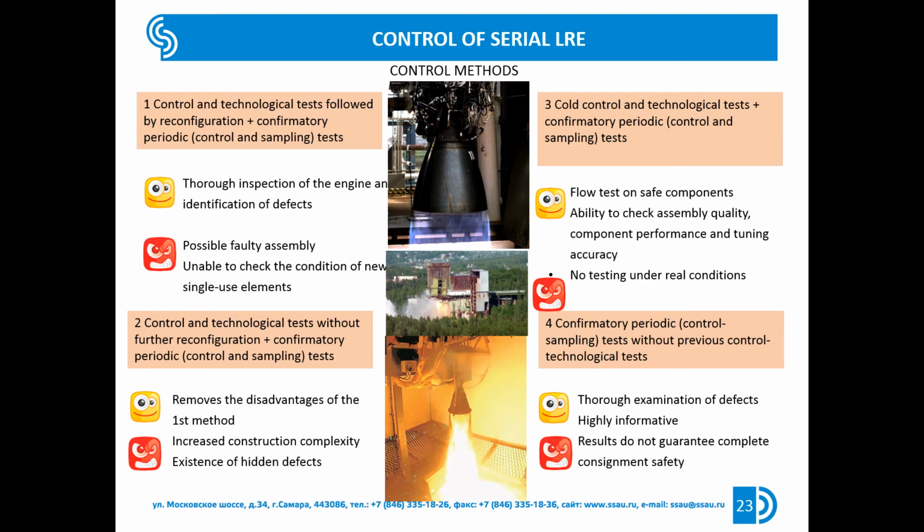This disadvantage is eliminated by the second method. However, in this case, additional requirements are imposed on the design of the LPRE and its post-test processing methods. The LPRE must be capable of multiple burns even if it is intended for single use.